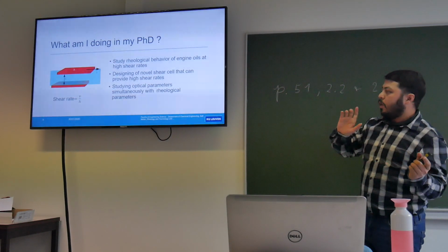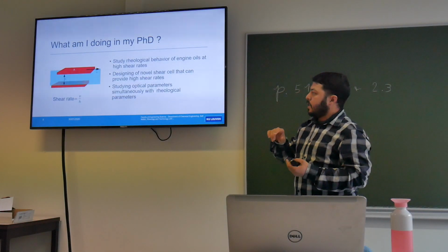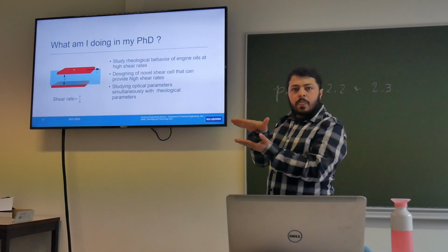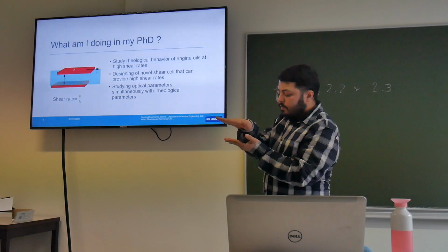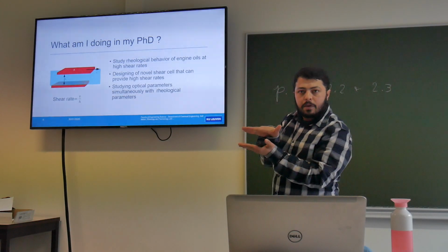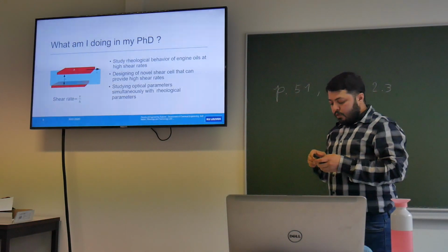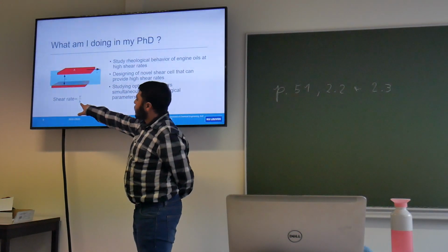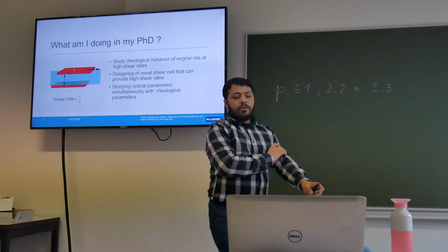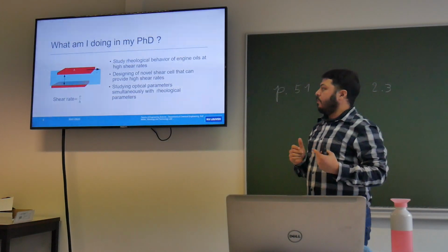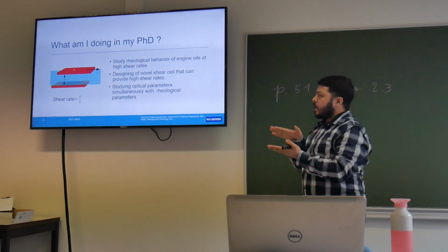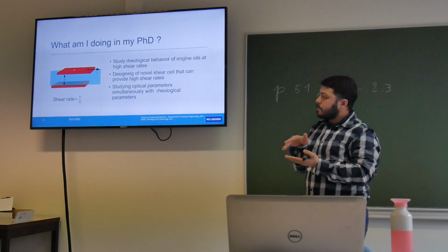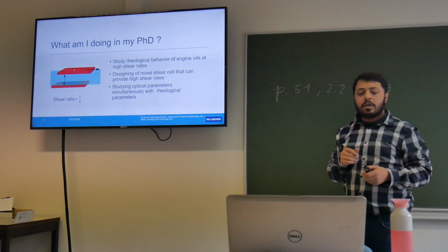What is shear rate? If you are not clear, just look at the example over there: you are shearing your material. So you have a speed with which you are shearing and you have a measuring gap in between. If you want to increase the shear rate, you can either decrease this gap or increase the velocity. If you increase the velocity, the flow becomes very abrupt. So the idea is that we go for smaller gaps that will give us increased shear rate.